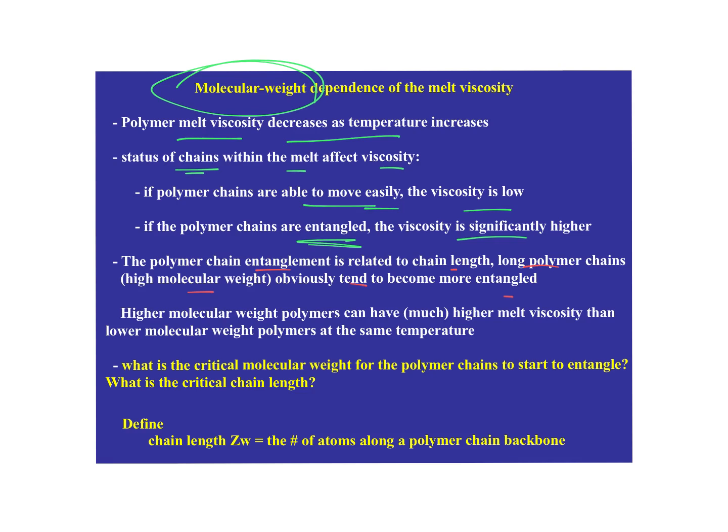Again, shouldn't be a big surprise. But as it turns out, this is one of the issues, and we'll see some consequences in a minute, that higher molecular weight polymers can have a much higher melt viscosity than lower molecular weight polymers at the same temperature.